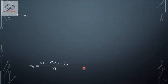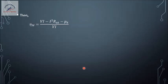Considering this assumption, what we get is the efficiency of the motor, where wherever there was Ia in the previous equation, we have replaced it by I. So this term Ia square is now I square. Now let us separate out the terms by dividing throughout with the denominator. We get VI by VI is 1, I square Ra by VI gives I Ra by V, and Pk by VI. So this is the equation which gives us the efficiency of the motor.